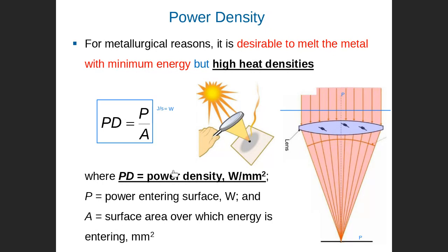So let me emphasize again: in welding, we are not looking for power or heat, but we are looking for power density or heat density. Any question, guys?